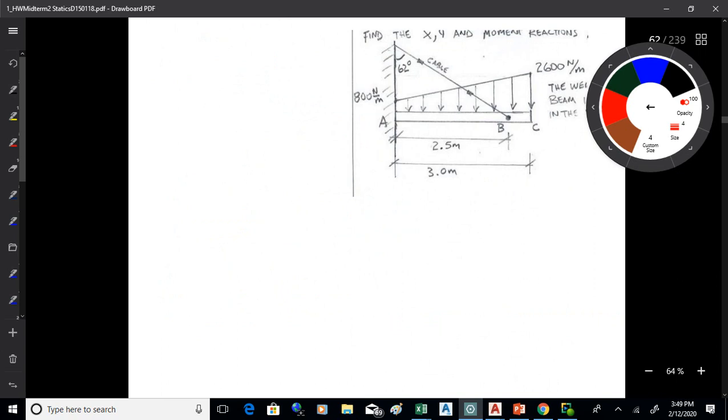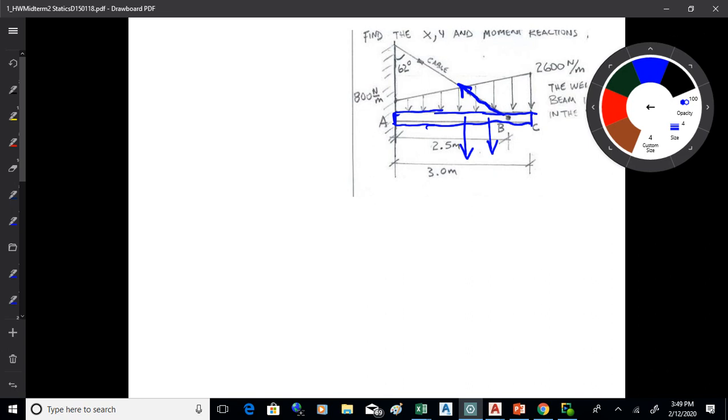All right, now when I'm doing these, I just think of these as processes of breaking things down. So what I have here is this beam. I'm going to have 2 loads on it. I'll probably put them underneath just to stay out of the way of the cable. And I've got the cable. So I want to come up with a free body diagram of this thing. So I've got 2,700, and make sure that I got that right, and 2,400 newtons.